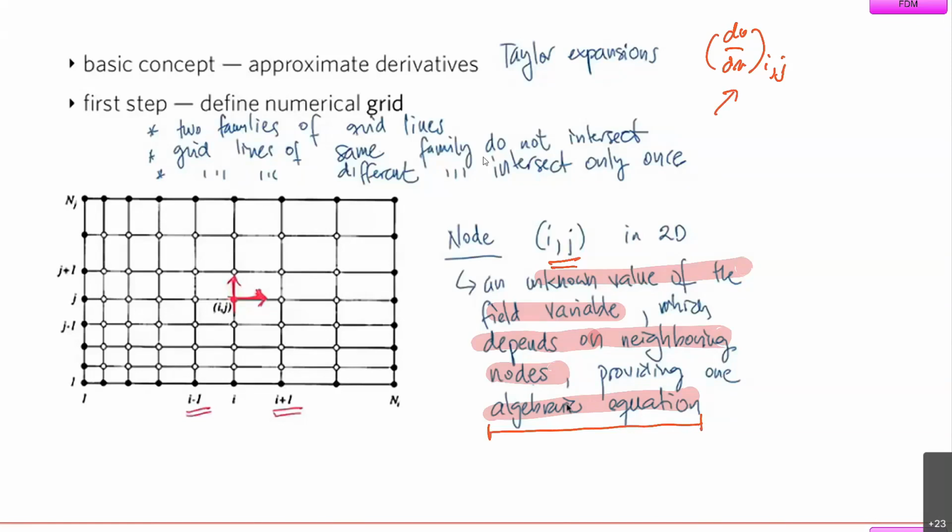Remember, the purpose of discretization is to change the form of a function into algebraic equations that are easier to be understood by the software or by the user. And these algebraic equations are basically an approximation of the real function. So that's the key here.